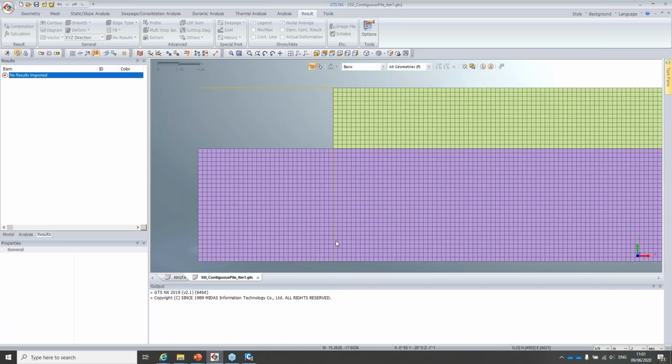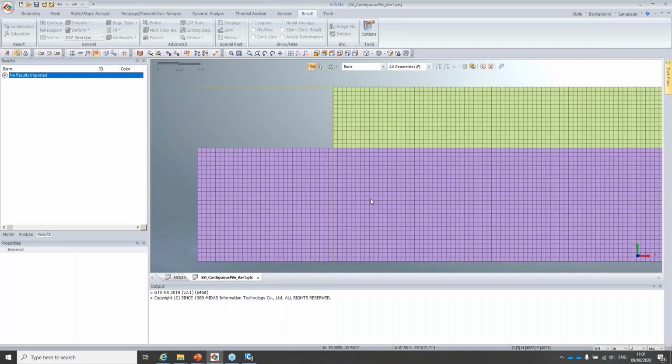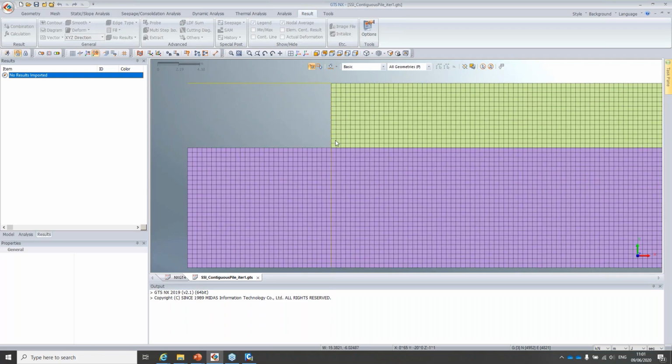What I've avoided doing in this example, and what you probably need to do when you're doing that yourself, is having an interface element here, which basically represents this friction value that you can expect between the ground and the pile, both on the abutment and also the pile that is embedded on the clay. And what research finds is for assessing the K-star and the pressures on the backfill, an upper bound on this friction value is the most onerous one.